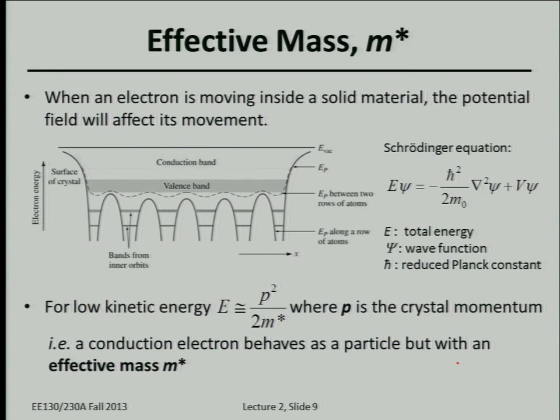That turns out to be a pretty accurate way to model electrons and holes moving around in a crystal if the kinetic energy is not very high. The effective mass in a crystal is different from that of an electron in free space, but if we exert force on it, it will accelerate. It'll have kinetic energy, one half mv squared, proportional to momentum squared, except this m has to be modified. I'll mention next time how people experimentally find this effective mass value.